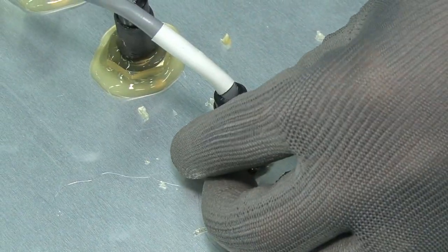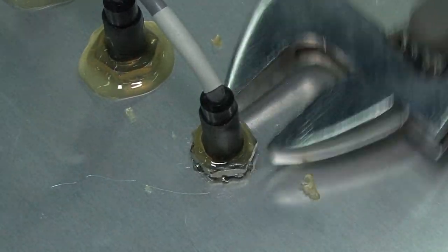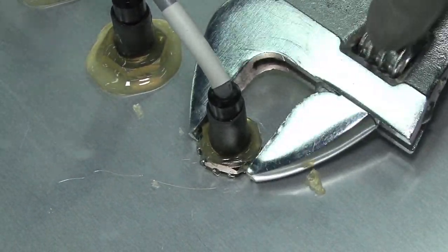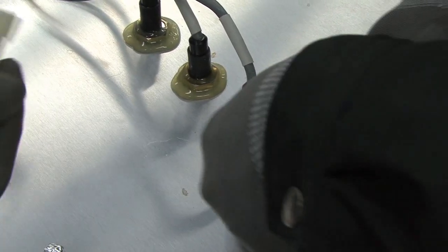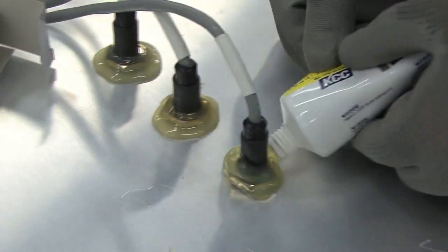Step 4. Check the order of lamp wiring of power, run, fail lamp and assemble connector. Step 5. Close the cover after arranging the lamp wires evenly in the capacitors. Step 6. Tighten the cover using bolts. Step 7. Check if power lamp light is working properly.